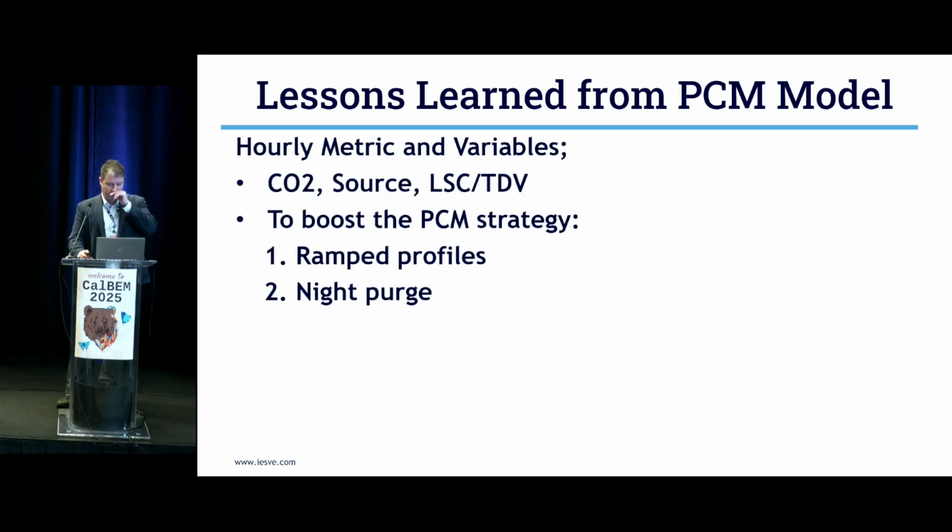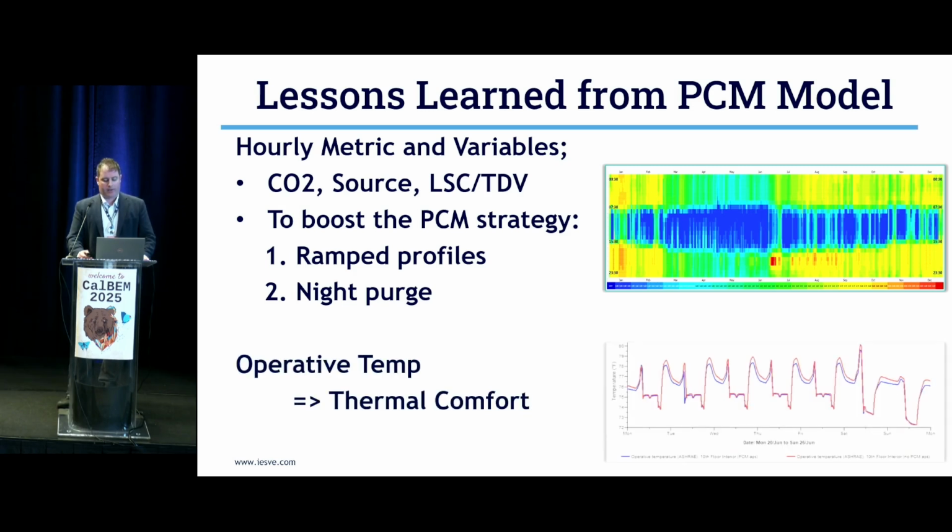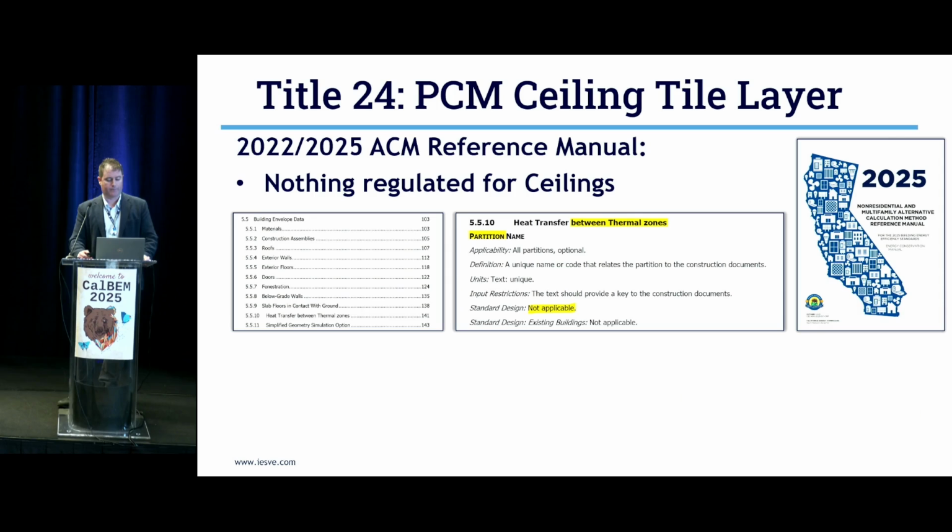The second lesson learned is you must account for hourly and even sub-hourly analyses. This technology works really well during the hourly condition. You'll also get benefits on things like operative temperature, right when the building is becoming occupied or unoccupied. The best energy metrics you'll see will be when you account for hourly source factors, hourly carbon emission factors, or something like LSC in the future.